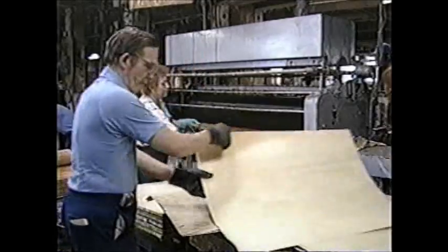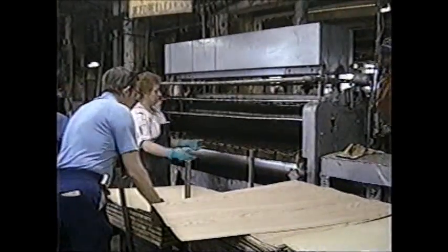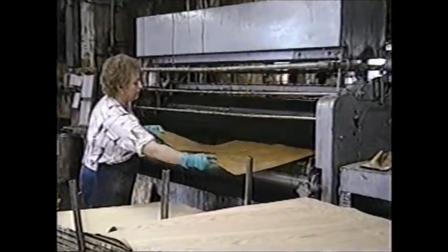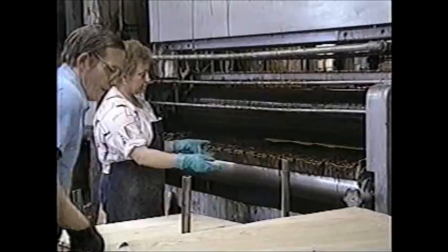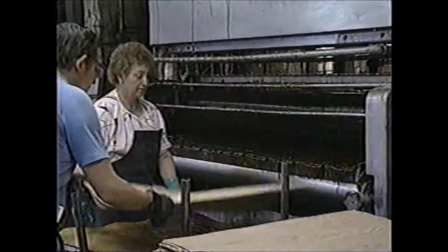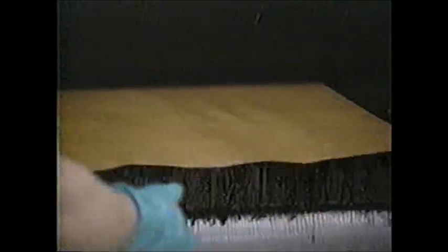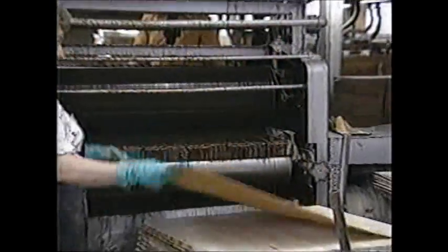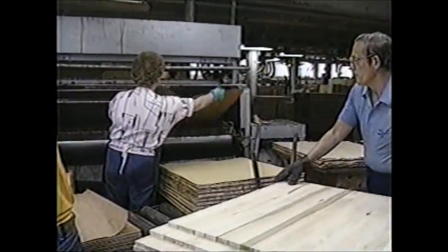In constructing a lumber core panel, note that a sheet of face veneer, unglued, is put in place, then a sheet of core veneer glued both sides, then the lumber core, then a sheet of double glued veneer, then 2 sheets of face veneer. One is the back for the piece just completed. The other is the face for the next panel.